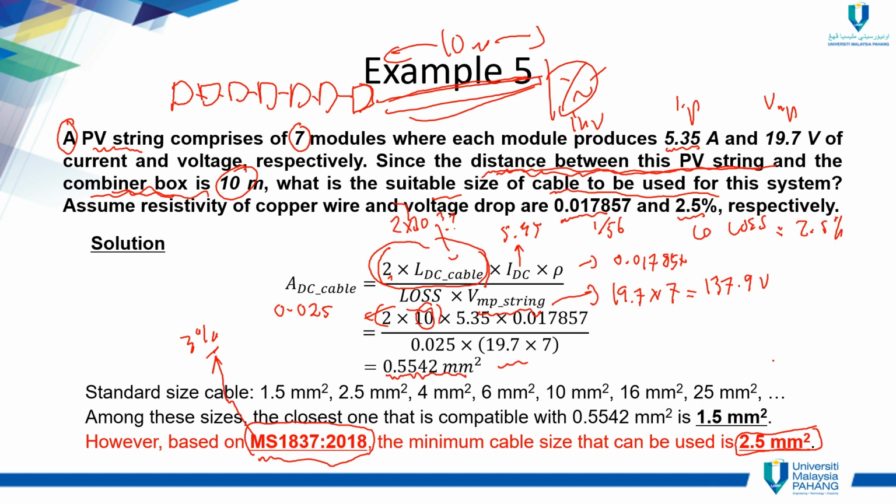But for the case of DC cable, because we are grounded by this standard, so there's 2 items here. One is the 3% of voltage drop, allowable voltage drop, and another one is the minimum cable size to be used is 2.5 millimeter square, not the 1.5 millimeter square. Boleh? Okay. Walaupun saya dah terminate, boleh minta kerja hantar resume balik lah. Macam tu. Boleh? Boleh minta kerja balik.